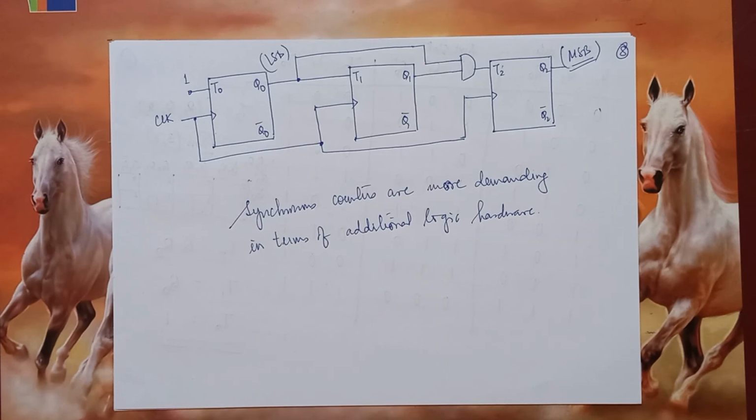Synchronous counters, you can design them without having to worry about what type of flip-flop it is, so long as you know its excitation table. Therefore, any counting sequence you want to design, you can design it using any flip-flop that you have, as long as you know its excitation table, and you can design any sequence that you want.